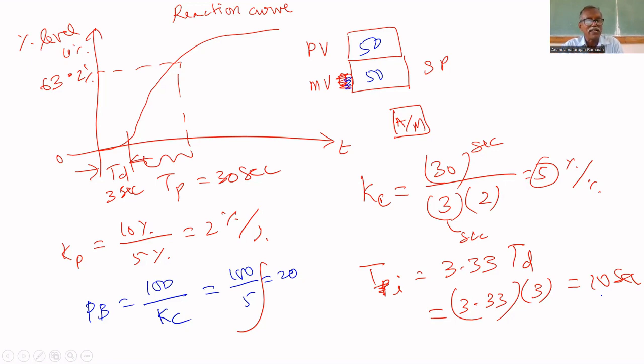When it displays set point, you can adjust it with increase and decrease, and if you press enter, the set point will be accepted. So you made set point equal to PV, the process is at steady state, and you entered the correct tuning parameters, whatever you calculated. Now the process is ready to transfer from manual mode to auto mode.